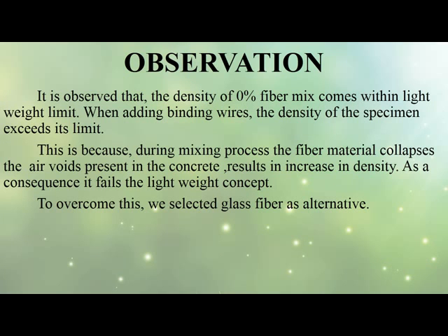From density, it is observed that the density of the 0% fiber mix comes within the lightweight limit. When adding binding wires, the density of the specimen exceeds its limit. This is because during the mixing process, the fiber material collapses the air voids present in the concrete, resulting in increase in density. As a consequence, it fails the lightweight concept. To overcome this, we selected glass fiber as an alternative.